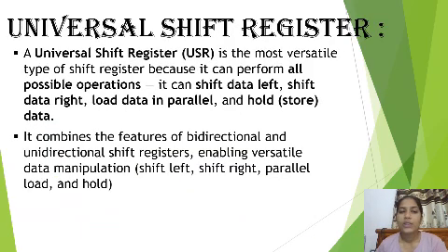The last one is the universal shift register. A universal shift register is the most versatile type of shift register because it can perform all possible operations. It can shift data left, shift data right, load data in parallel, and hold data. It combines the features of bidirectional and unidirectional shift registers, enabling versatile data manipulations like shift left, shift right, parallel load, and hold.